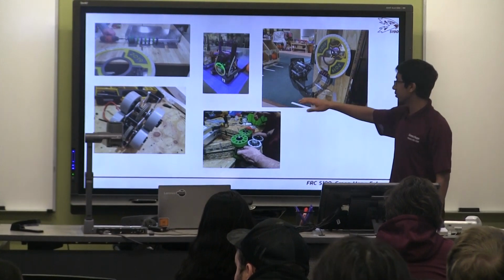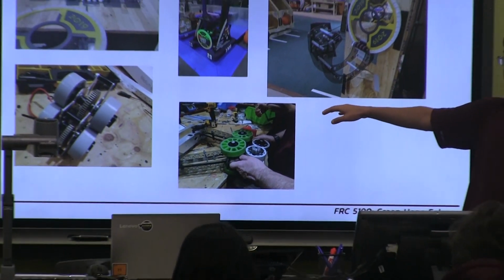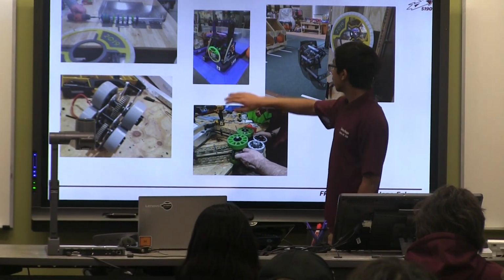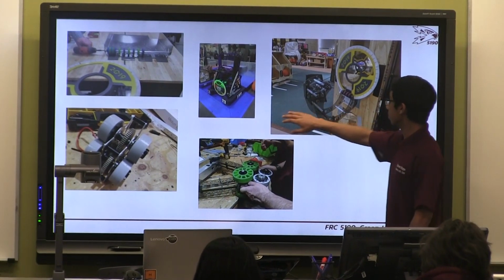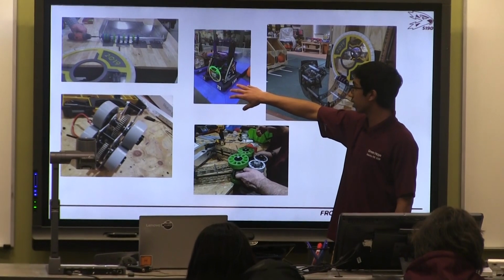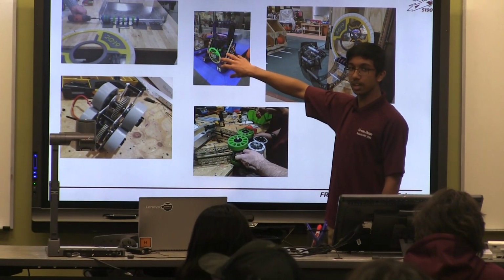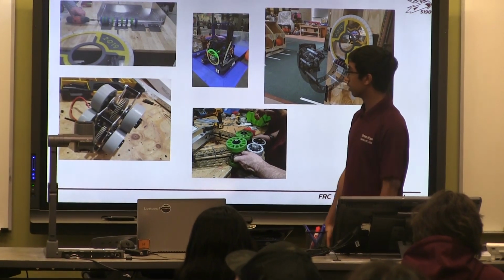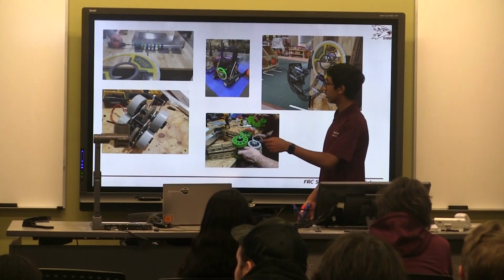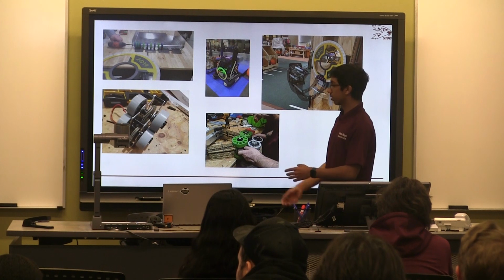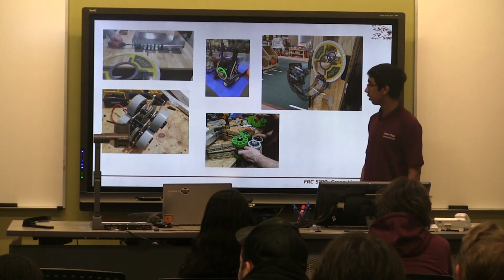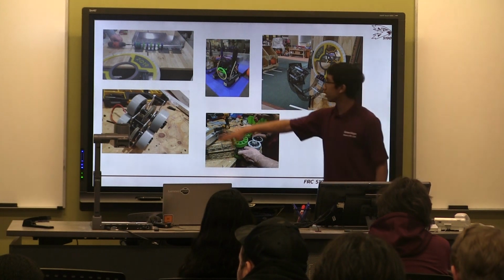We looked at a bunch of wheel intakes after build season ended, and we thought, oh, this is a field that we should explore. Basically, 3 of these mechanisms revolve around the concept of intaking the hatch from the inside using wheels. You spin the wheels outward and then the hatch will move in, because the diameter of the wheel is equal to the distance between this edge and that edge. So that's how those 3 mechanisms work.